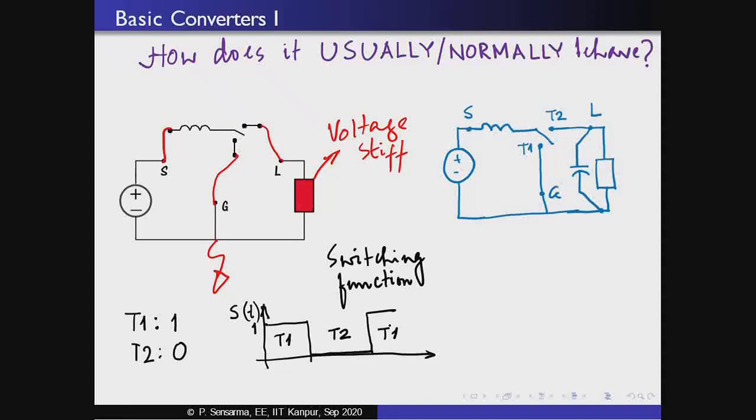That is because this switch is the element that, just by its very nature, is always supposed to toggle between these two positions. Now, if it keeps on toggling between these two positions, you would expect the voltages and currents applied to various parts of the circuit to constantly change with time. So, that definition of steady state where variables are constant does not really apply to a switch mode circuit or to a power electronic converter. So, what is the sensible definition of steady state when we are talking about power converters?